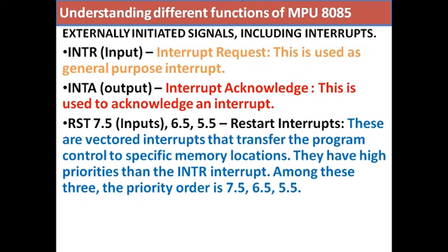So in order to save the microprocessor's precious time, the interrupt driven data transfer scheme was introduced, where if data is available at any port of the input output devices, it will first request the microprocessor by sending a signal through INTR.